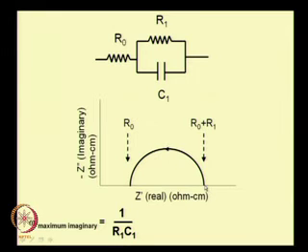So this is at a very low frequency, and as you go to higher and higher frequencies you get to this point. In all intermediate frequencies, for that omega you get the actual value of the impedance, the specific value of minus i by omega C, and then you have to treat these two as impedances in parallel. So 1 by R and 1 by minus i by omega C will be in parallel. So you will get an impedance for this, and correspondingly you will get all these points. We have seen a good justification for this point and this point. If you run through all the calculations you will get all of the rest of the points.